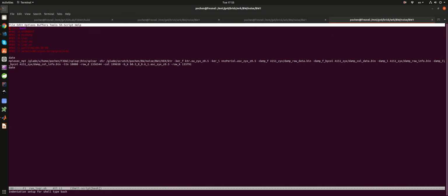So a few things, right? That's the parallel binary. And then the directory for storing all the kernel matrix, the right hand side, and the damping subdirectory for storing all the damping matrix. And then that's the assembled kernel matrix binary file, the 85 gigabyte file that I was showing you. And then the non-zero information file that was converted from binary to ASCII using the ZBA binary. And then the damping matrix that has to be referenced to the subdirectory inside of this particular working directory.